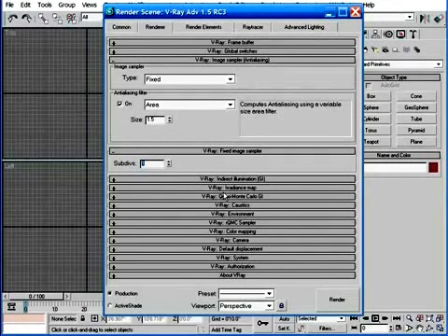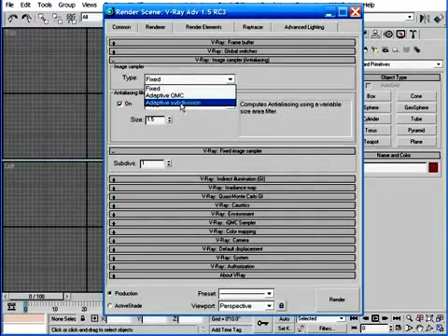And as a general rule, we only use this when 75% or more of the rendered image contains areas where we need this kind of high level of detail. And in these cases, we recommend using the fixed image sampler, but when that 75% percentage is not met, then we usually use one of the other two. And by not using the image sampler on scenes with a large amount, you run the risk of VRay guessing wrong as to which areas should receive greater sampling.